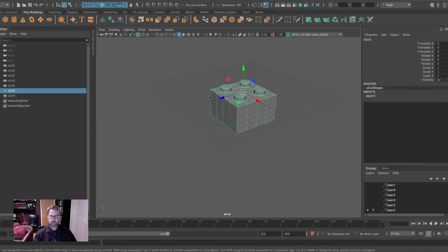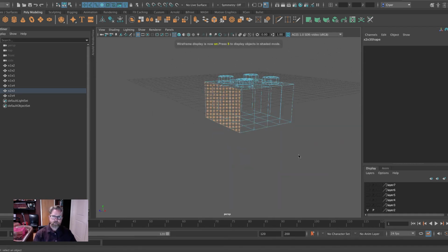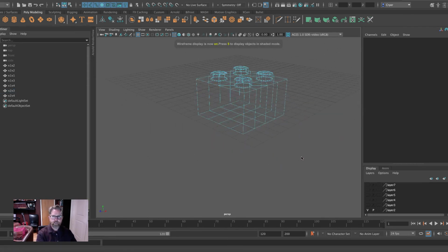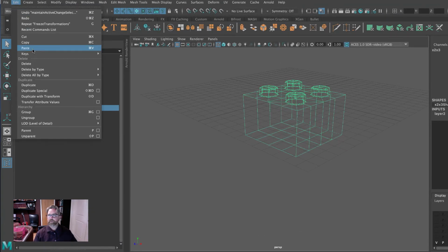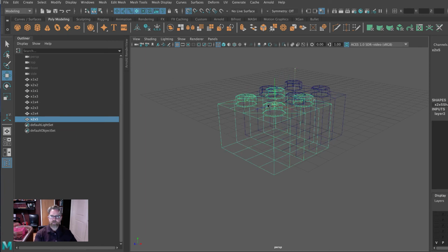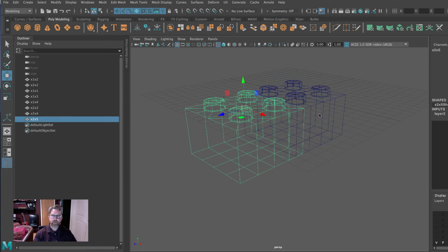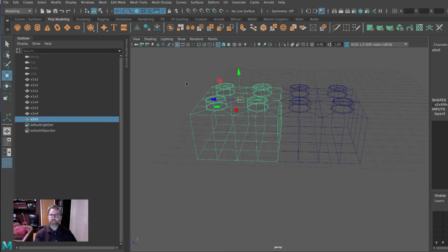We know that we're going to attach this, so I don't think I have to demonstrate that we need to delete those faces. We'll take a look around, right? We'll hit delete. We'll select this as an object. We'll come to duplicate. And because the pivot's at the top, I can use this perspective view to grid snap out. That was one of the reasons we wanted that pivot at the top, so that we didn't have to jump into the orthographic view.